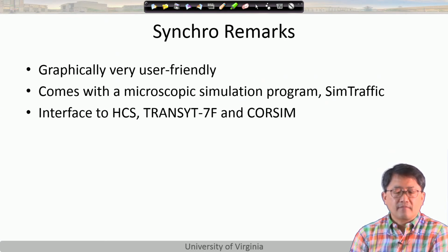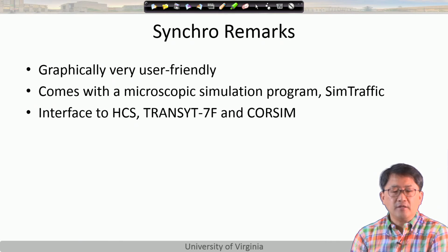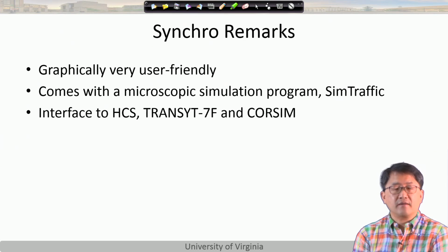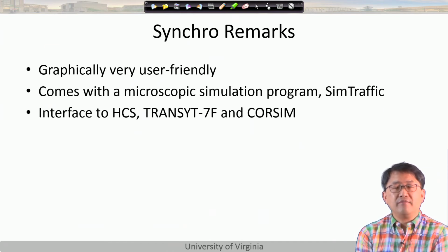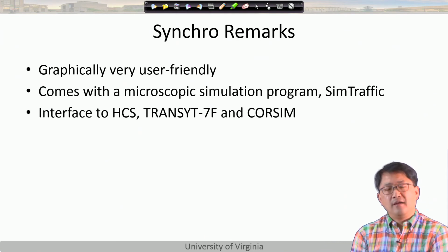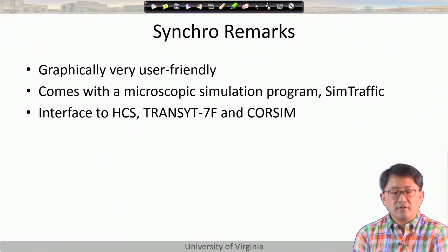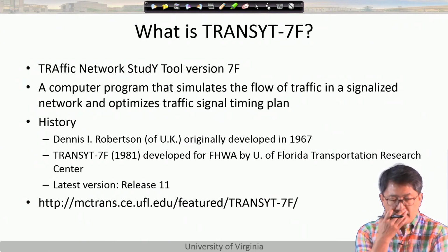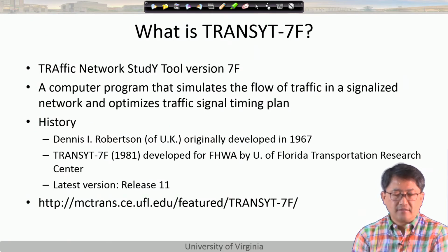But it's very commonly used and has a very nice graphical interface. And it does have actually microscopic simulation, the so-called SimTraffic. So whenever you have a Synchro network, you can actually run microsimulation one click away. They figured out all the inputs you have in Synchro, and they can actually run a microscopic simulation. That's good. It has an interface with other tools. So that's Synchro, and I'm going to talk about TRANSYT-7F for just another 10 minutes.